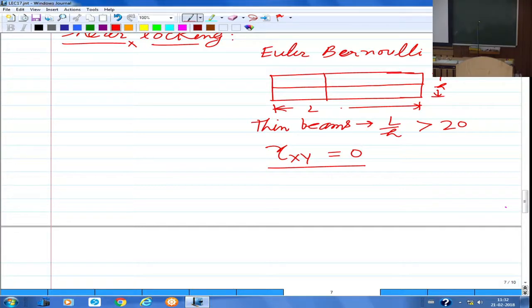By doing this, the deflection is significantly less. You can do the same thing: hold this side but put a paper clip which holds this together, and you will find that the deflection is significantly less. Because when I leave it like this, you would see that this normal, which was initially normal to the middle surface, is no longer normal to the middle surface, the actual normal has gone like this.